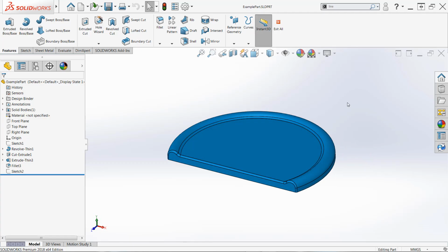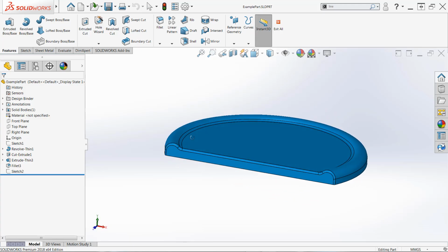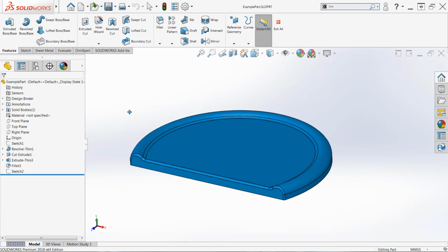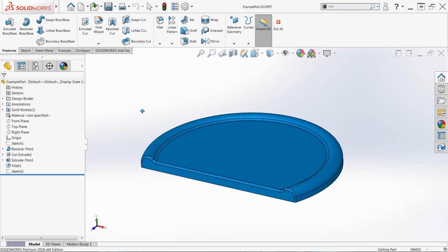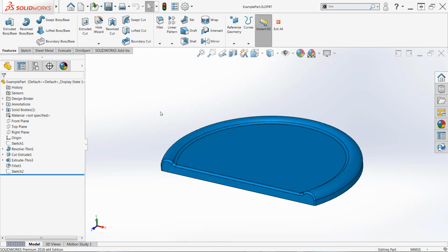And that can be a little bit difficult to get used to, so you want to get some practice with that. By the way, if rotation is activated while hovering over a piece of existing geometry, that point will remain stationary. So that's a good trick to be familiar with as well. If you hold Control key and do the same thing, click down on that center mouse wheel while holding Control and drag the cursor, you can now pan your model. And by the way, if you don't have a mouse wheel, you can use the center mouse button.